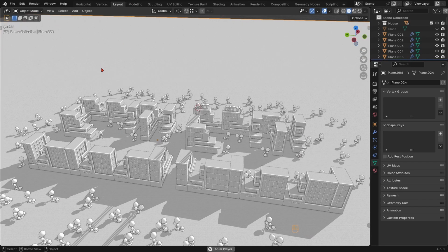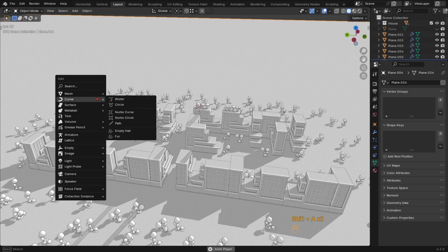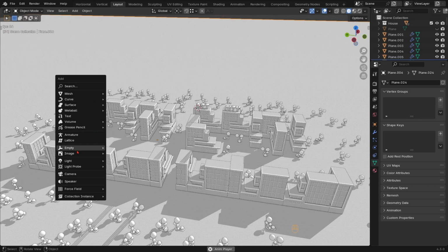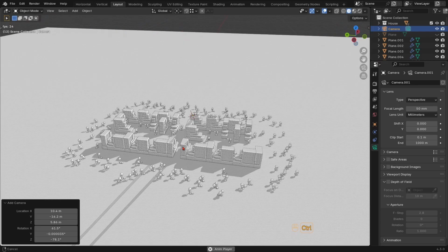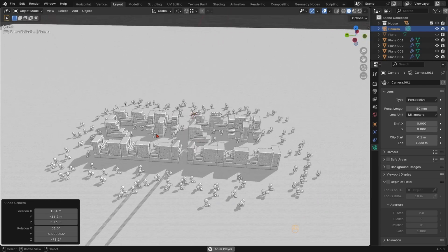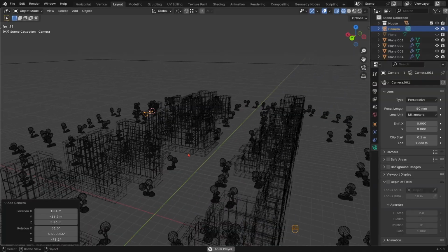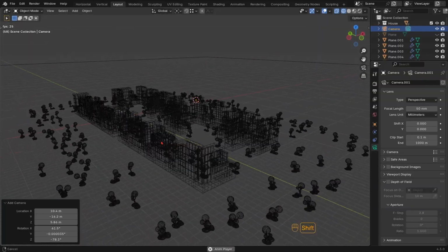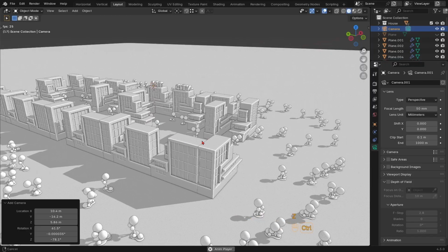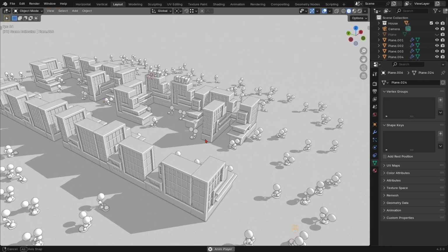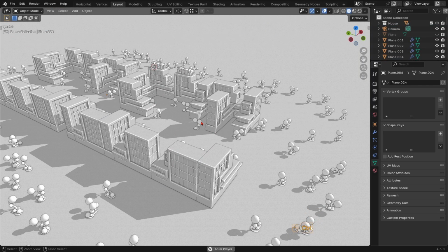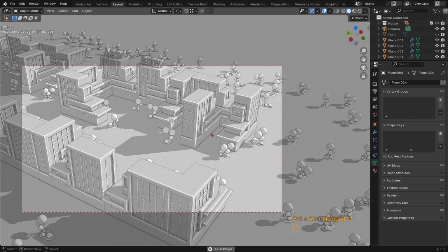So now let's press Shift A once again, and we can add some other stuff. Let's add a camera. And where is our camera? Well, the camera is at the place of the 3D cursor. Now I like to change my angle of view to something like this. And then I press Ctrl, Alt and 0. If I do that, the camera will be locked to the view.